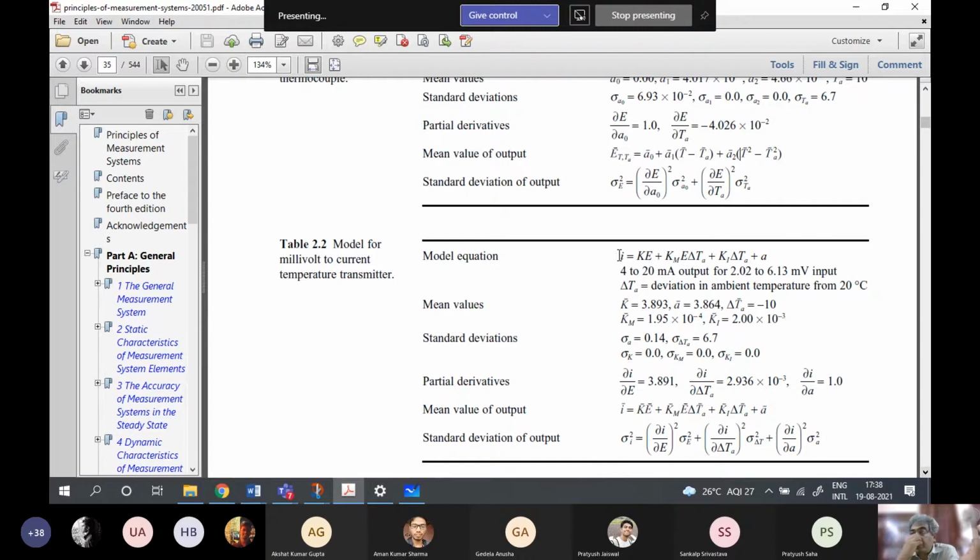Probably this temperature is being produced at some point, maybe in some welding, something is being welded, and you want to know the temperature around the welding, just arbitrarily saying. So the millivolt voltage is there. First of all, you have to make the signal stronger, and you have to get it to a place which is maybe slightly far away.